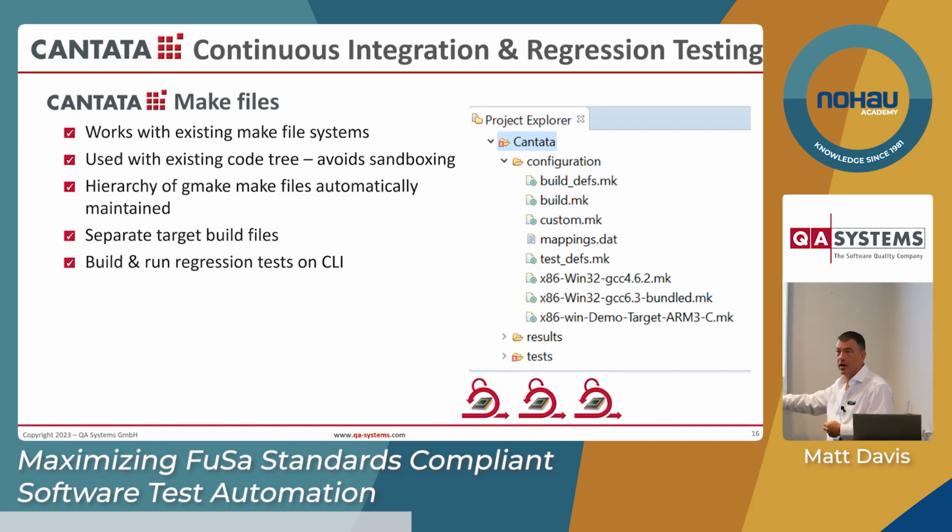If you are doing a Class A device or an ASIL A system, you can run all your tests host native. You don't even have to use a cross-compiler. But if your application is very heavily dependent on the physical environment, it's a lot of effort to simulate all of the behavior of that hardware, so you might run it on the target because it's faster and more efficient to do so.